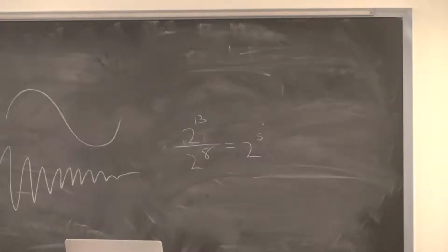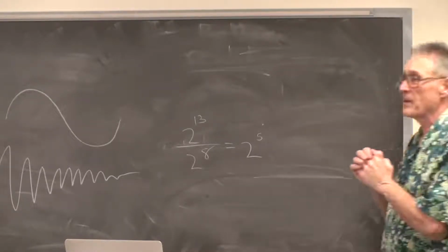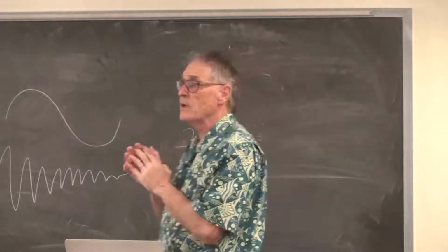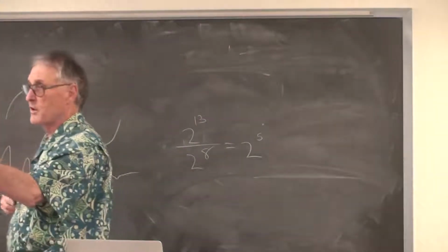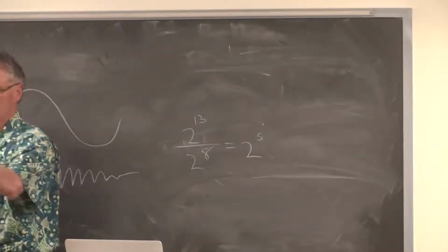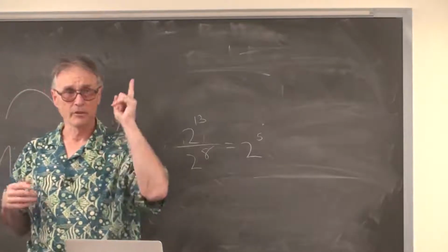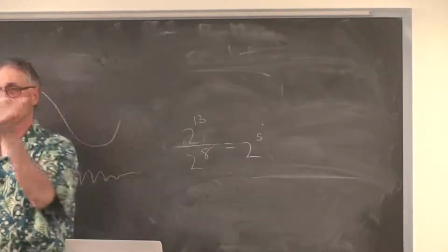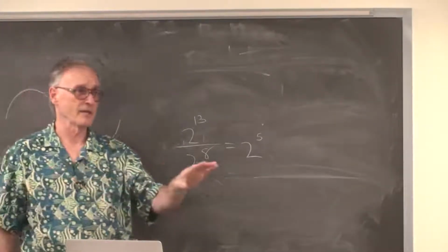If you look at the length of the register and count the bits, it's a 16-bit register. You can do 65,000 entries. You can have a table of 65,000 entries and send it in with one instruction from the CPU. Enable DMA. It goes for 65,000 entries before it stops again.